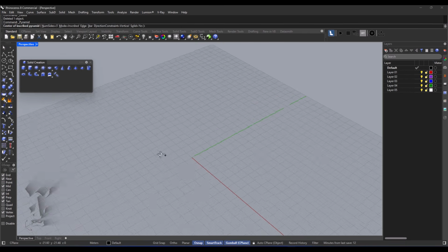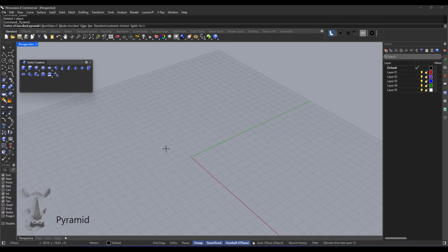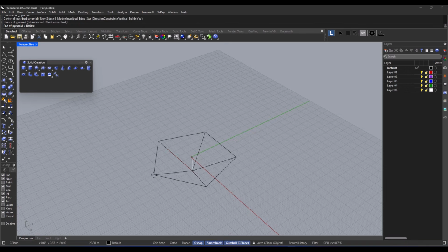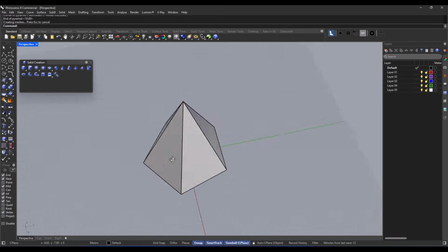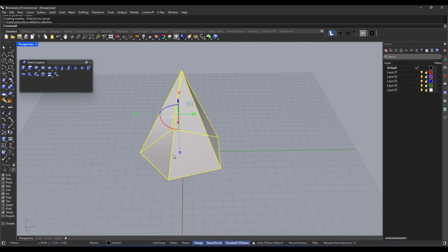Wild, right? And then you finish it off by drawing the end circle. Now let's talk about the pyramid. The pyramid command draws a pyramid. You kick things off by drawing the base polygon. Don't forget to check out the polygon command for all those option details. Next up, you pick the end of the pyramid, the apex, or just type in a value to set the height. Easy peasy. So yeah, that's how you do it.